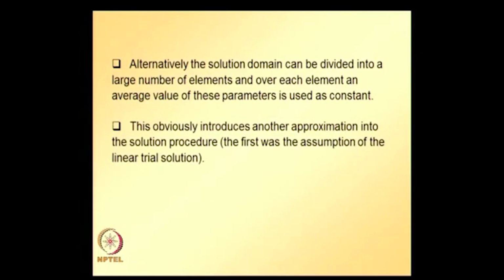So, now what we will be doing is taking an application of this general one dimensional boundary value problem, which is one dimensional heat flow. Basically, we derived the element equations for a linear finite element for a general one dimensional boundary value problem subjected to both essential and natural boundary conditions.